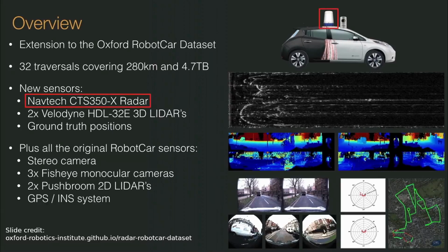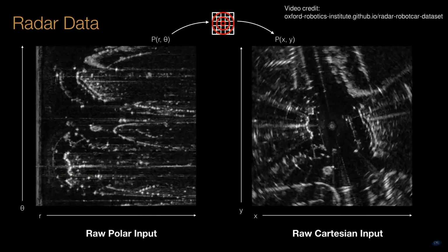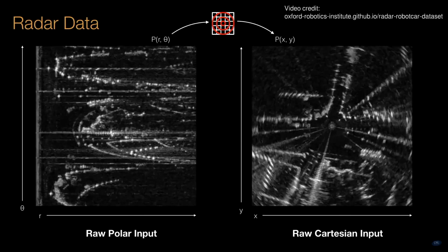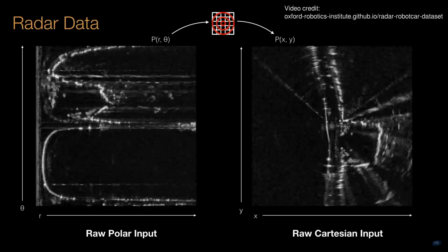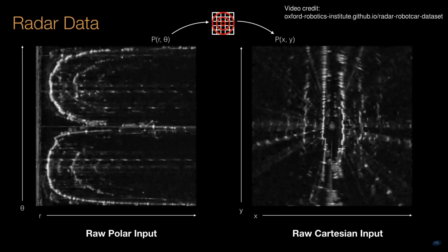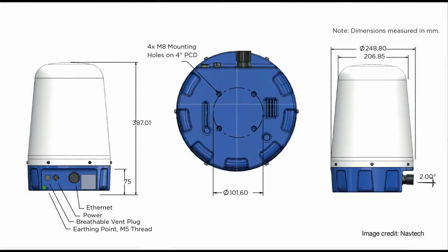Second, it uses a NavTech radar sensor. Now, the NavTech sensor produces these beautiful high-resolution radar images representing horizontal scans of the environment. These are excellent for some purposes, like autonomous driving, but they aren't really that useful for 3D state estimation or mapping. Lastly, the NavTech sensor weighs 6 kilograms and draws 24 watts, making it pretty unsuitable for small, agile platforms.